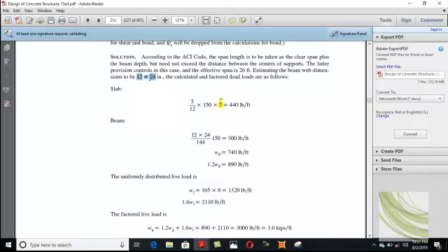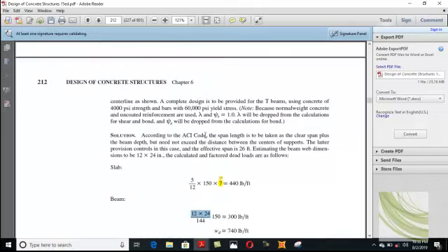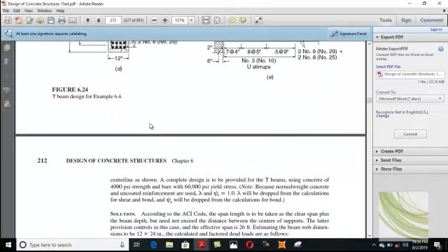Okay, you calculate the loads for heavier depths, okay, and you are providing lower depth. So this doesn't make any kind of difference. If you calculate the loads for lower values and you are using higher values of depth and width, then it is unsafe. If you are using lower value of depth and width and your calculation is basically on the basis of higher value, then you are on the safe side. Clear?